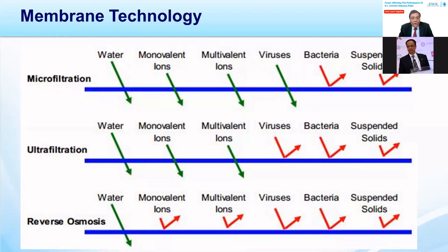Normally in our water treatment technology, we also relate it with the term molecular weight cutoff size, MWCO. The cutoff size of a molecule depends upon its molecular weight. In the water, all molecules are bigger than H2O. That is why the RO membrane has been specially designed. The second biggest molecule present in the water is sodium chloride, which has 23 plus 35.5, so 58.5